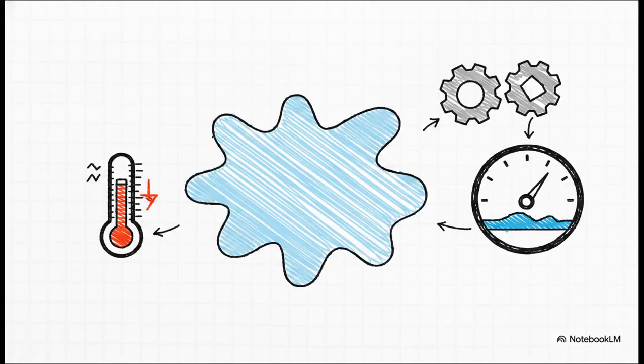Now, I have to burst the bubble a little bit here because as with everything in the real physical world, beta is not some static magic number. If we look closely at its characteristics, it actually fluctuates quite a bit. It varies depending on how much collector current is flowing. It changes directly with the junction temperature, so if it gets hotter, beta goes up. And crazily enough, because of manufacturing tolerances, beta will even vary between two identical-looking transistors pulled from the exact same batch. No two are perfectly alike.